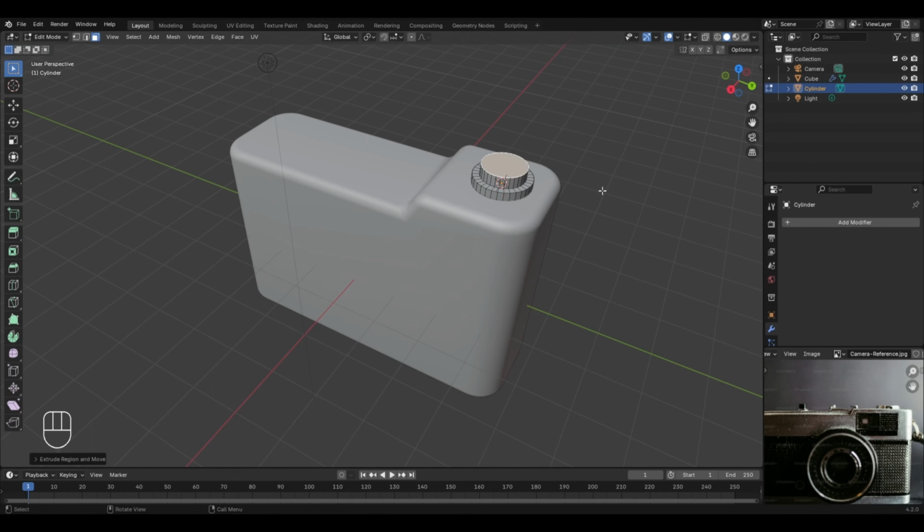After this, with the top face selected, press Ctrl plus B to apply the bevel tool, and if I move my cursor away, then you can see that it is already having a particular number of segments which it has taken depending upon the last time we used the bevel tool. And yes, you can also check the number of segments on this top left corner where it shows that the number of segments is equal to 8, and the offset, which is basically the bevel effect which I can change by moving the cursor away and towards the cylinder, also gets displayed along with the number of segments.